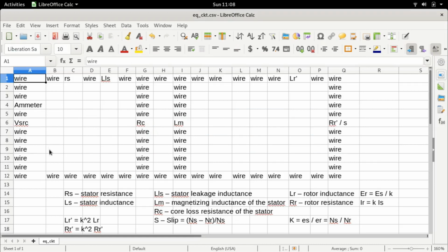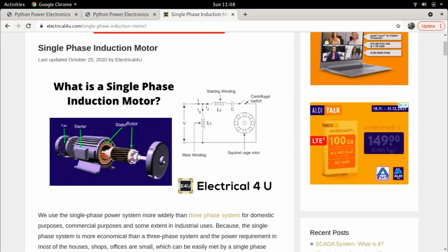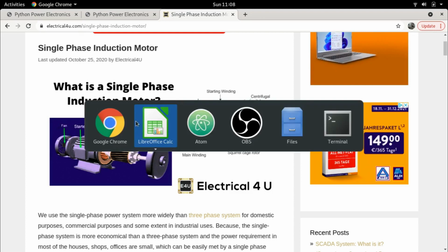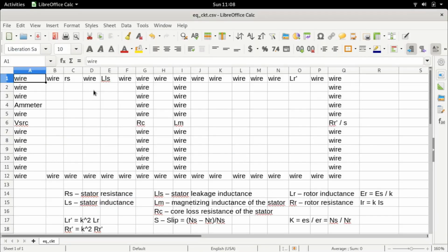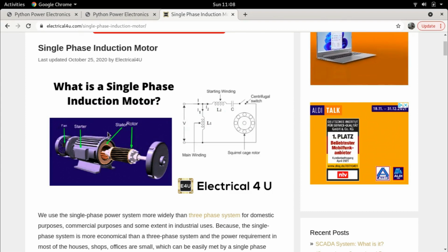This voltage is being applied here. The voltage which is being applied will result in current flowing in the stator windings. But not all the current in the stator winding will result in useful flux in the air gap. Some of it will leak. And when we are talking about leakage, the leakage could be anywhere. It could be somewhere outside, so it doesn't go into the air gap, it goes somewhere else.